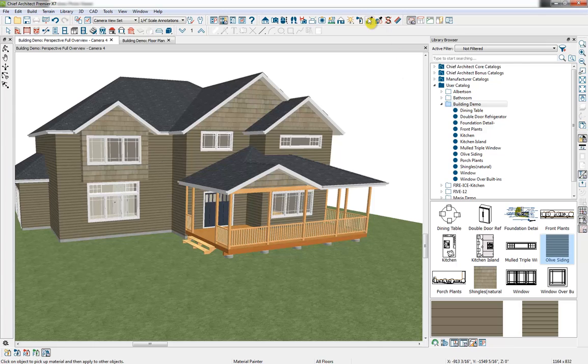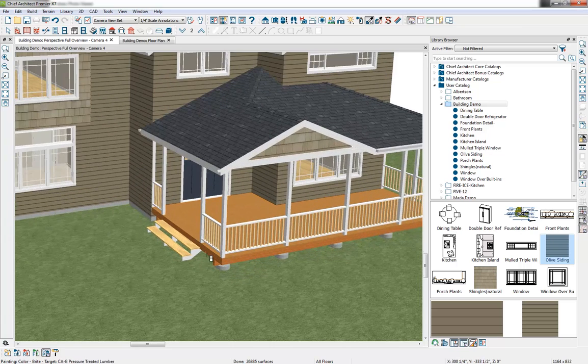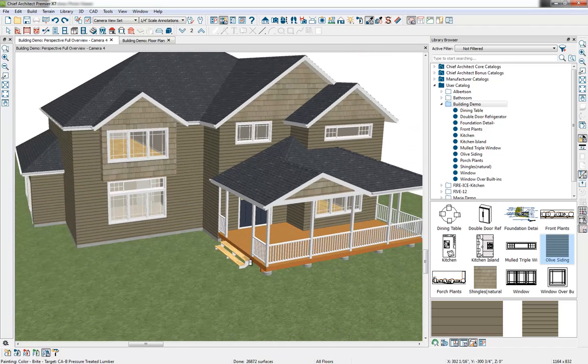Next, I would like to match materials. So I'll use my material eyedropper, click on the white so I kind of absorb that white trim, and I'm going to apply that onto some of our different materials here on the porch. Let's do our balusters here. And the stair material is a very similar material to some interior flooring that I have. So I'll get right back into component mode, so I only change these stairs instead of the stairs on the interior as well.